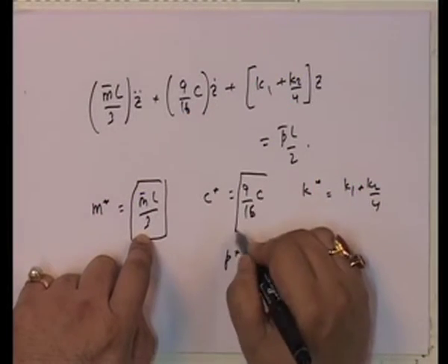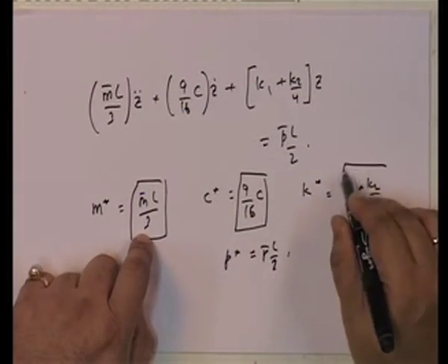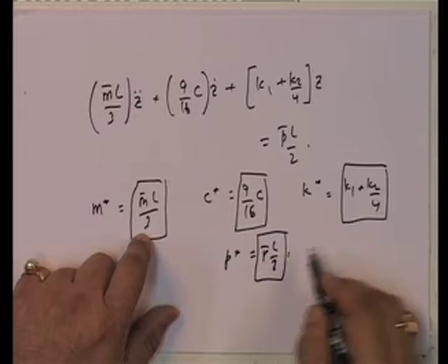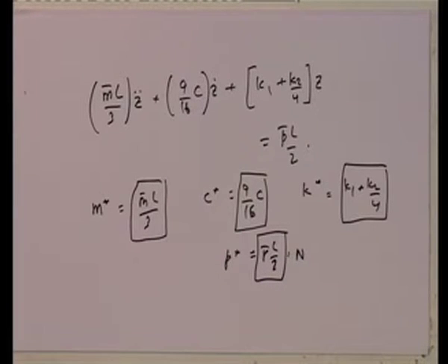Okay. Now, if z, which is the displacement, is my degree of freedom, then what is my m star? If you look at it, m bar is kg per meter. So, kg per meter by kg, it means this is kg. This is Newton second per meter. This is Newton per meter. This is Newton per meter, this is Newtons. So, if you look at it, the entire equation essentially becomes very, very clean.